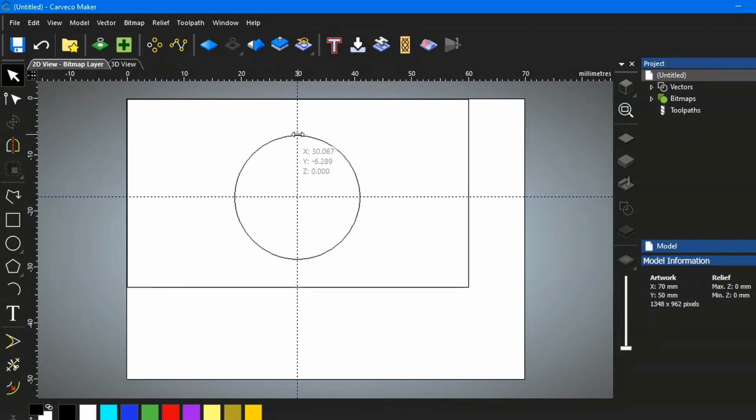Obviously the distance between here and here is crucial, because the ball screw is going to be in the center here, and the main upright from the gantry is going to be bolted to this, so there's an absolute measurement between the top of this and the center of this, to not bind or anything like that, so the screw can actually move freely.